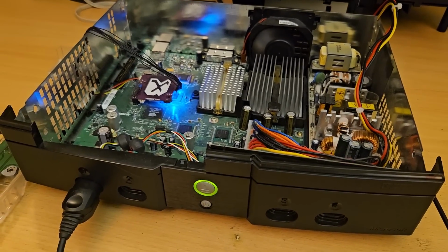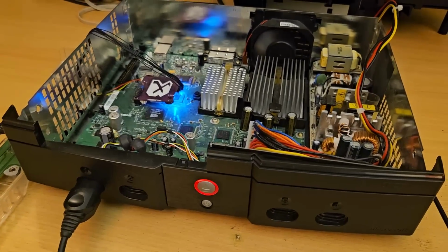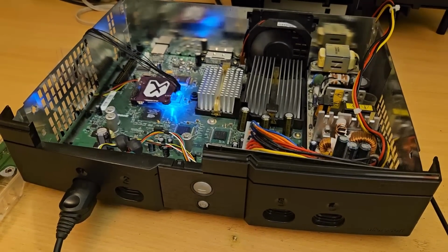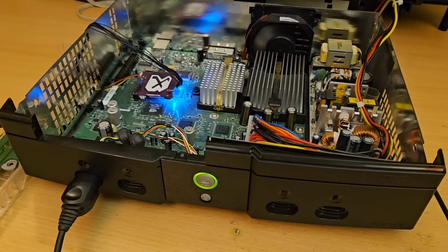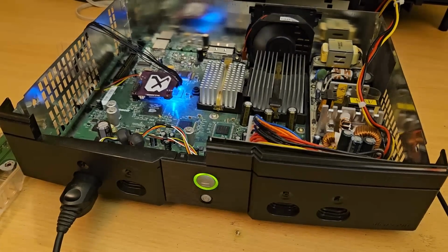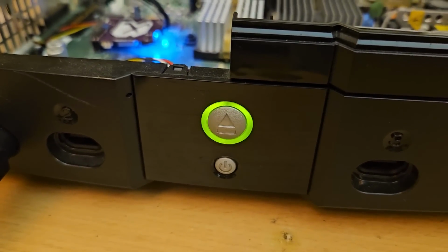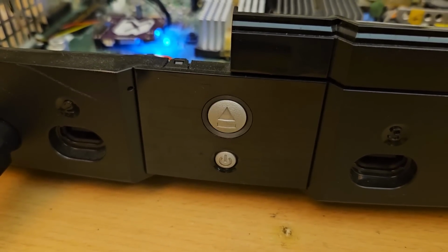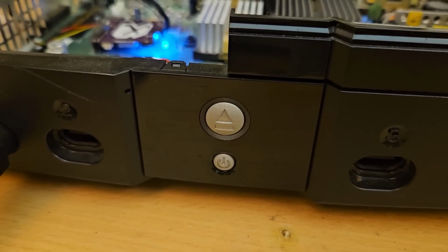In this case, that red, green, off blink is telling me that chip 2 has failed. This RAM test BIOS is based on flash code. So instead of copying code in flash to RAM and then executing it there, we keep the code in flash and we execute it from flash. This means that I don't need working memory for this BIOS to boot and be able to tell me which chip is failing. For the production test Xbox, I made a separate BIOS. Very similar though. It will just test a single chip, and it tests the entire memory of that single chip.